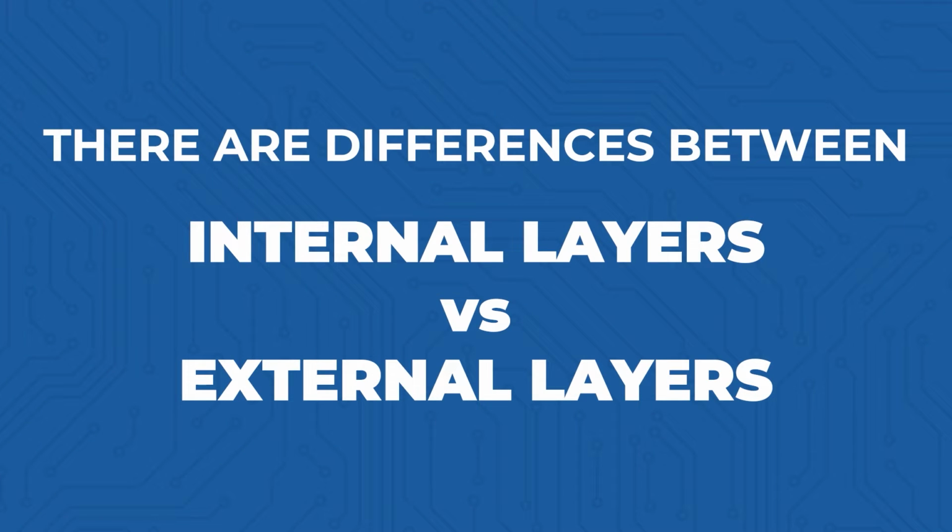For one thing, for doing your power routing, typically that's best if you do that on the outer layers, because the outer layers can carry more current through the signal traces for the same width compared to internal layers. And that's because the external layers, the top side and the bottom side, are exposed to air. They get airflow over them. That helps to keep those traces cool, because that's what will limit how much current you can drive through a PCB trace. It depends on how quickly or how much the trace heats up until it catastrophically is damaged or melts.